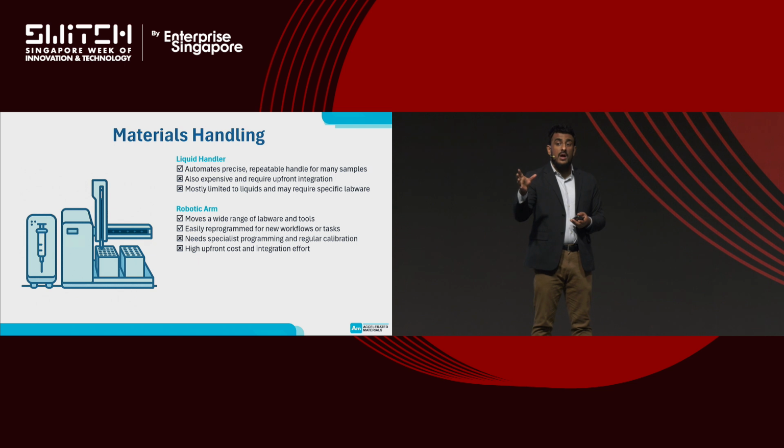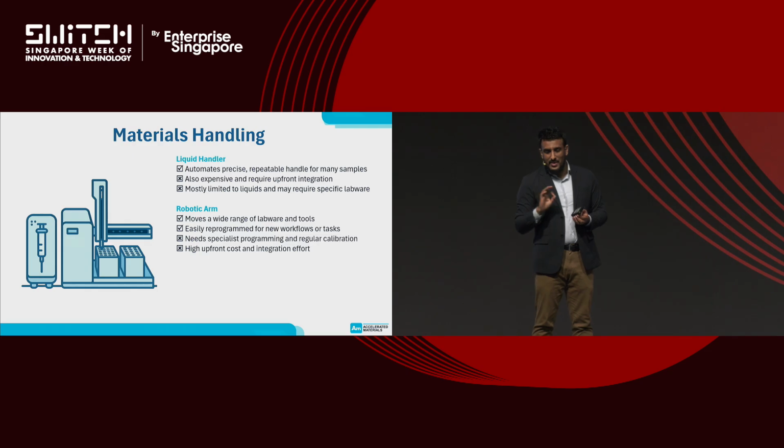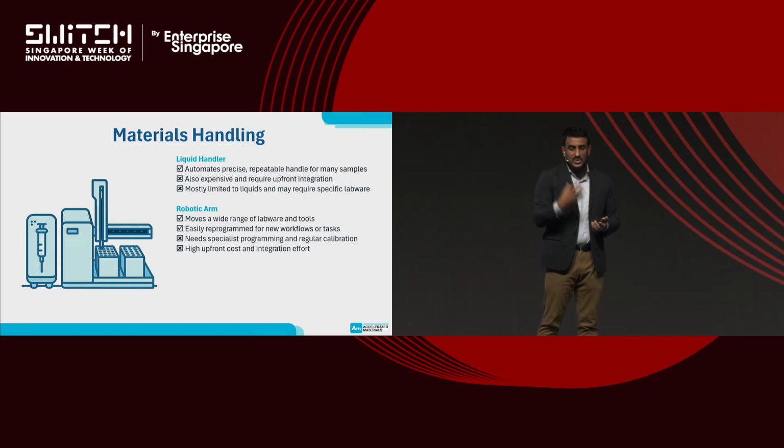Next, you can have a robotic arm. So you just have a simple pot of stuff, and the robotic arm will put it onto the hot plate. And when it's done, the robotic arm will pick it up and move it aside. Now, I know a lot of people like using robotic arms, and for people who haven't used them, it seems like a really versatile solution. But in my opinion, they can sometimes be difficult to program. Trying to get it to detect the flask and pick it up can sometimes be a pain. And even though they seem very versatile, often you can only get it to rigidly move this from here to here. It's not like a remote control, and it's not completely smart. It can't just do anything at any time. So once your robotic arm is in there doing a particular process, that's it, it's locked in there.